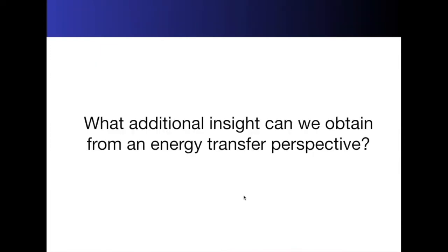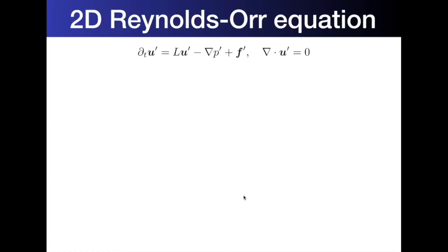So, cylinder flow has been analyzed to death, but what I want to ask is what additional insight do we get from looking at energy transfer? I'm just going to start with the 2D Reynolds-Orr equation. Everyone will probably be familiar with the 1D version for turbulent flows.